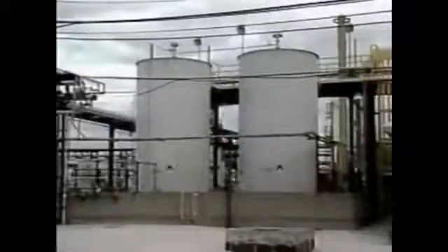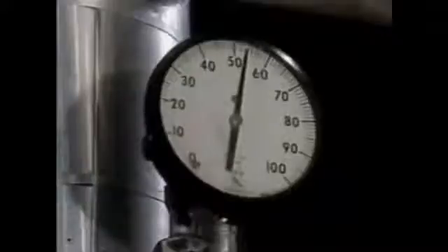For example, pumps draw liquid from these tanks. Before a pump is started, an operator checks to make sure that the liquid in the tank that feeds the pump is above a minimum level to ensure that there will be enough suction head to prevent cavitation. In a different situation, operators monitor a pressure indicator to help maintain the inlet pressure for a pump. In this case, the value for minimum net positive suction head is converted to units of pressure.